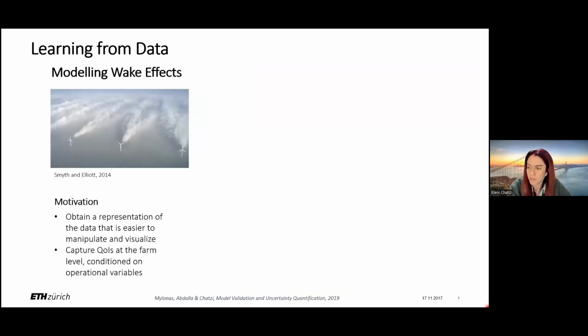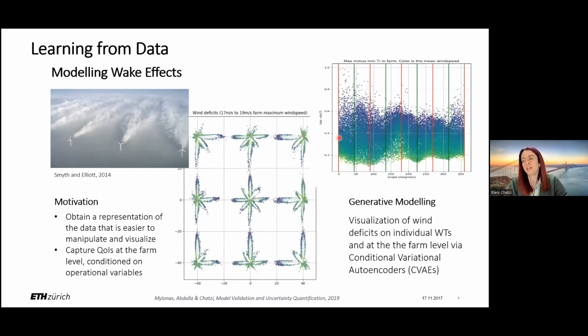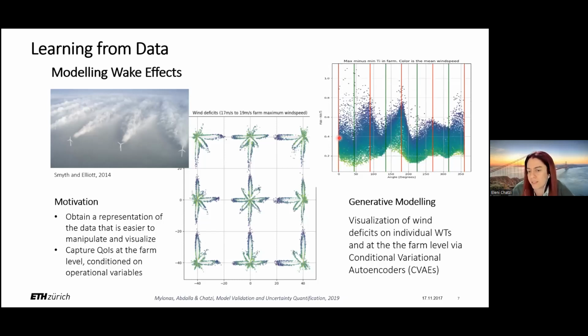Something similar for us also is achieved in the domain of wind energy monitoring, where we gather data, so-called SCADA information, at the nacelle of the wind turbines. This is something very typically gathered from these systems, where we have information on the mean wind direction, speed, and also power production quantities for each and every one of these turbines in a wind farm, and where we would like to achieve tasks that have to do with the assessment also of the loads that are experienced by these wind turbines, loads that have to do with their fatigue life, for example, that are useful for the engineers in order to understand interactive effects within the farm.